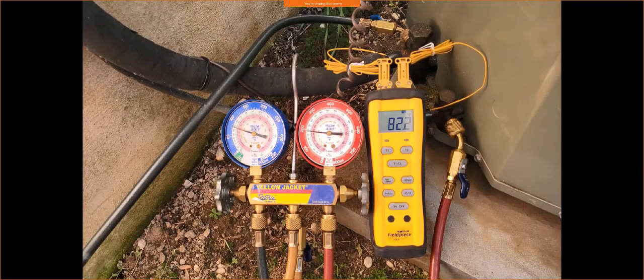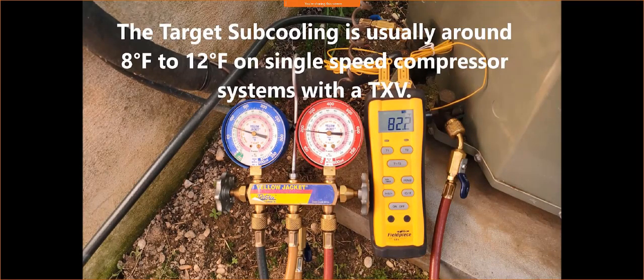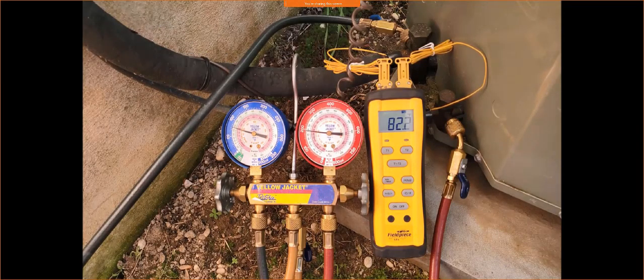The target subcooling is typically going to be around 8 to 12 degrees, but I have seen some rating plates read 19 degrees of subcooling. I have seen some that read 7.9 or 8. So the thing is, the majority of the outdoor units say 8 to 12 degrees of subcooling.